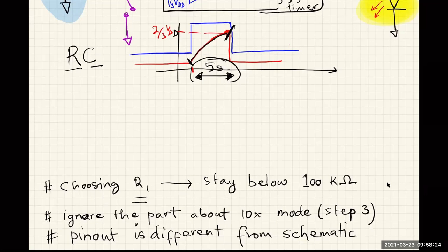So if you remember that an oscilloscope or voltmeters also have some resistance associated with them, which is closer to 1 mega ohm. So if you have a large resistor in your circuit and you're making measurements close to that resistor, then the act of measurement alone can change the circuit and make your circuit behave differently than what you expect it to. Okay.